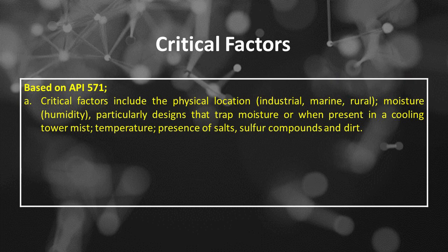Atmospheric corrosion critical factors based on API 571. Critical factors include the physical location, industrial, marine, rural, moisture, humidity, particularly designs that trap moisture or when present in a cooling tower mist, temperature, presence of salts, sulfur compounds and dirt.